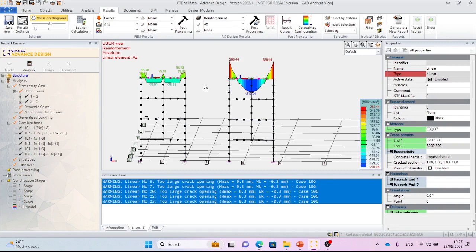So performing an analysis with the frame on the right-hand side, the user will add a great amount of reinforcement that is in essence useless, according to the second option, the left-hand side, where the construction phases have been considered and the load has been transferred properly to the different structural elements, and the time-dependent properties of concrete have been taken into consideration when doing the analysis.